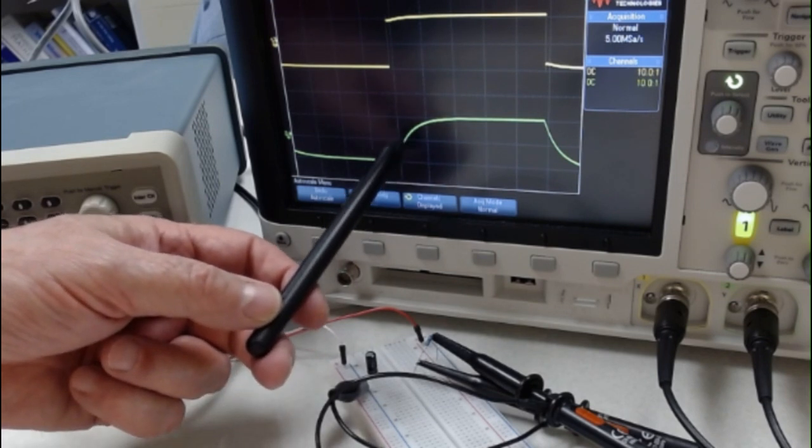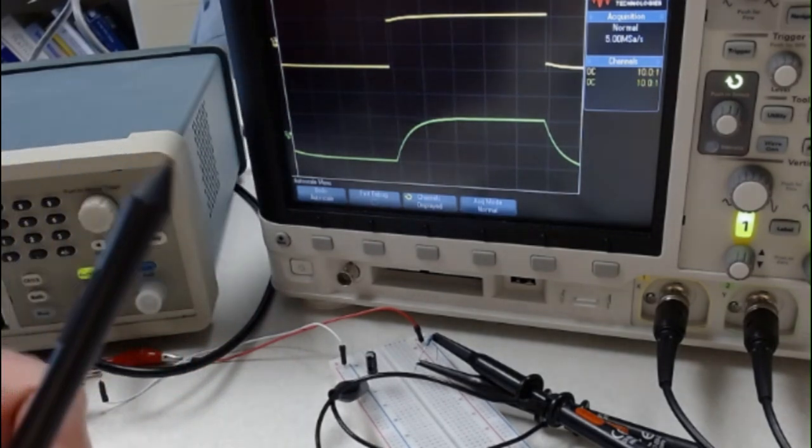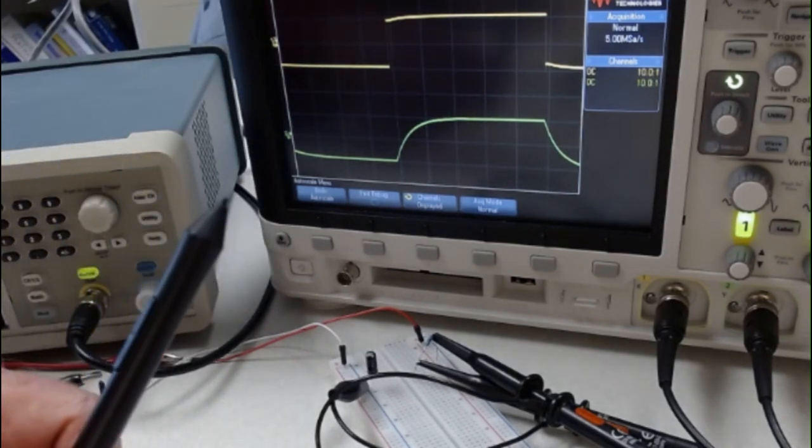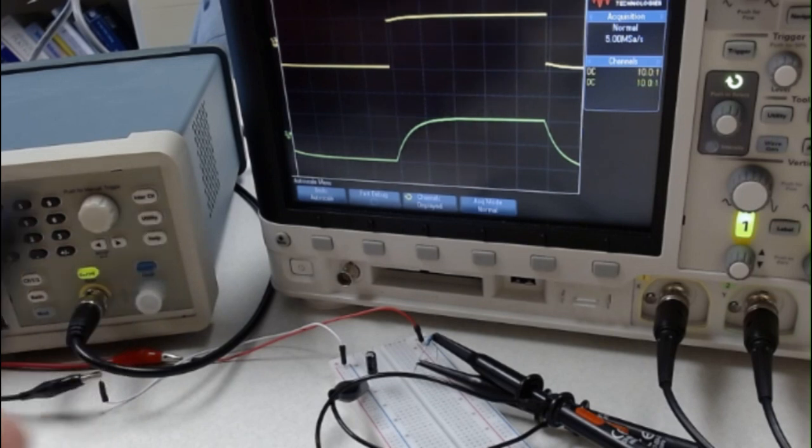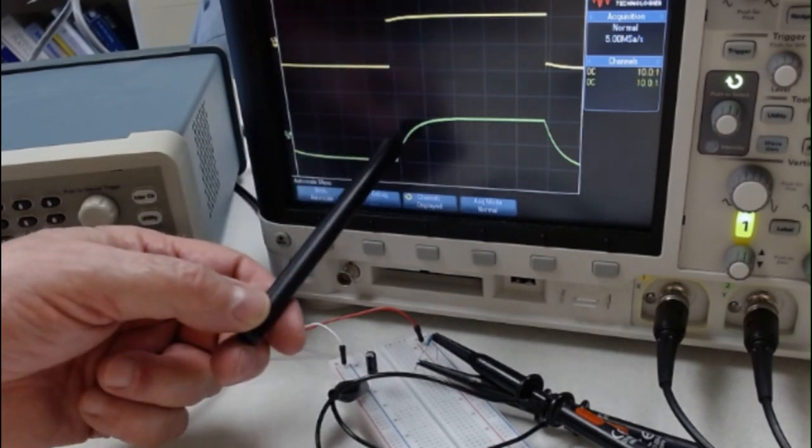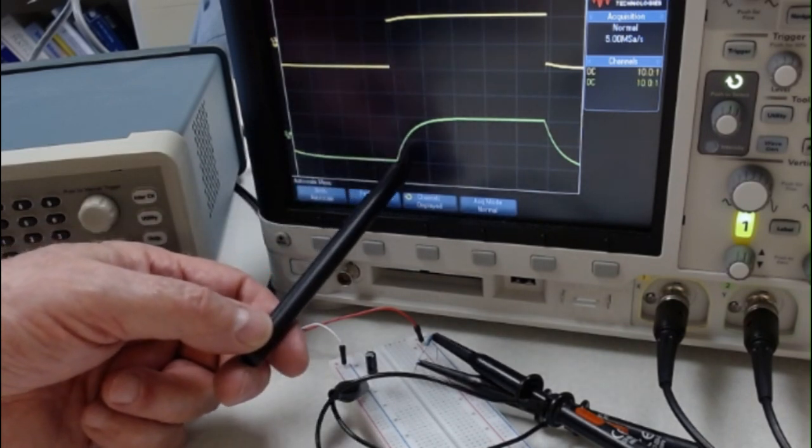So basically, our time constant, tau, or RC, is roughly 3 milliseconds. And if we multiply our numbers out, 10 times 10 to the minus 6 times 470, that's 4.7 milliseconds, or a little bit longer than that, but it's in the range, so we're close.